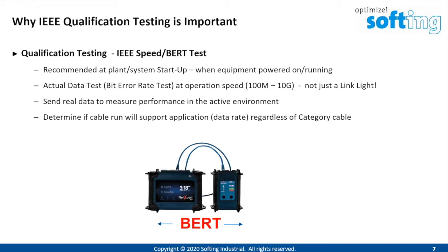So in the Ethernet standards, as I mentioned earlier, certification is having a tool that essentially says the cabling was terminated properly, it's the proper length, and it can support a certain frequency over the cable, which equates to a certain speed. But it's also often done at the beginning, when things have been installed, not when things start up and machines turn on and interference is encountered in the network.